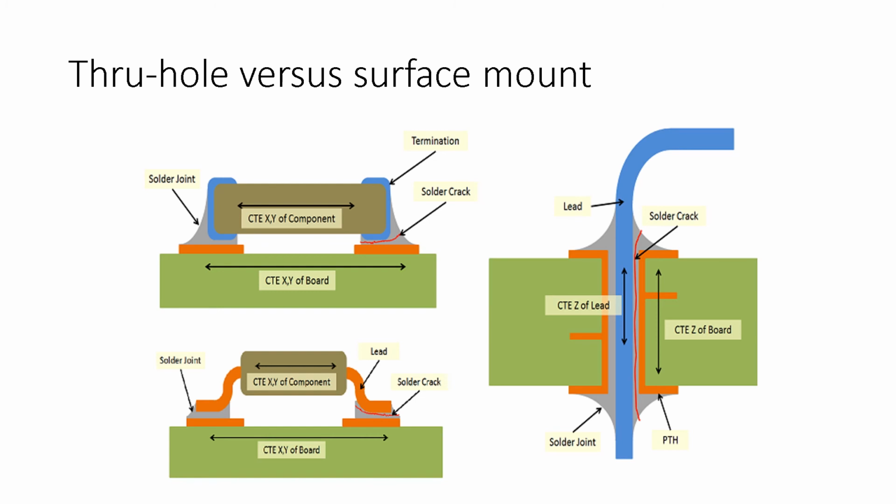And even the thermal cycles when they get soldered, so like wave soldering usually goes through, and essentially wave soldering, you heat the entire circuit up and you run some solder over top of it. But wave soldering lets a lot of the components get hot too. And sometimes for wave soldering, you can go through 10, 15, 20, even more thermal cycles, depending on the types of parts that you have on the board. So one of the big things for mechanical engineers is to look at the solder fatigue analysis of those circuits.